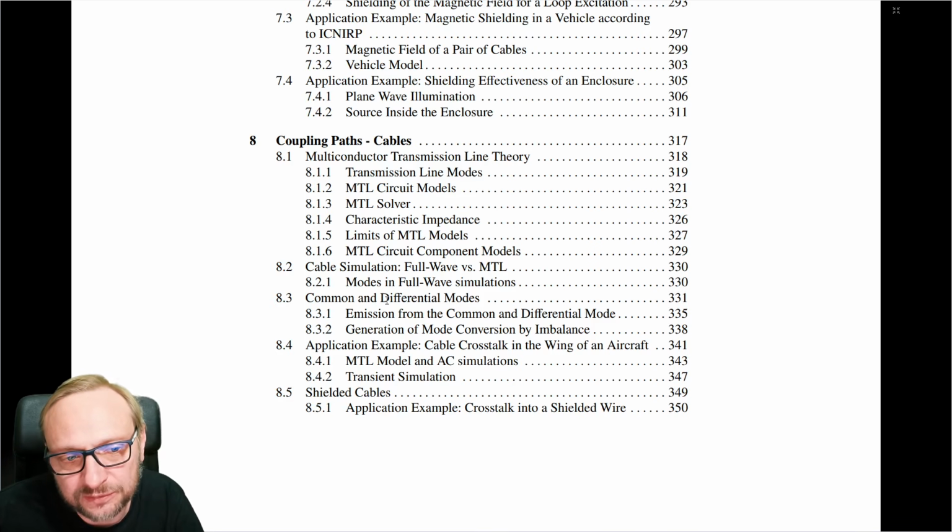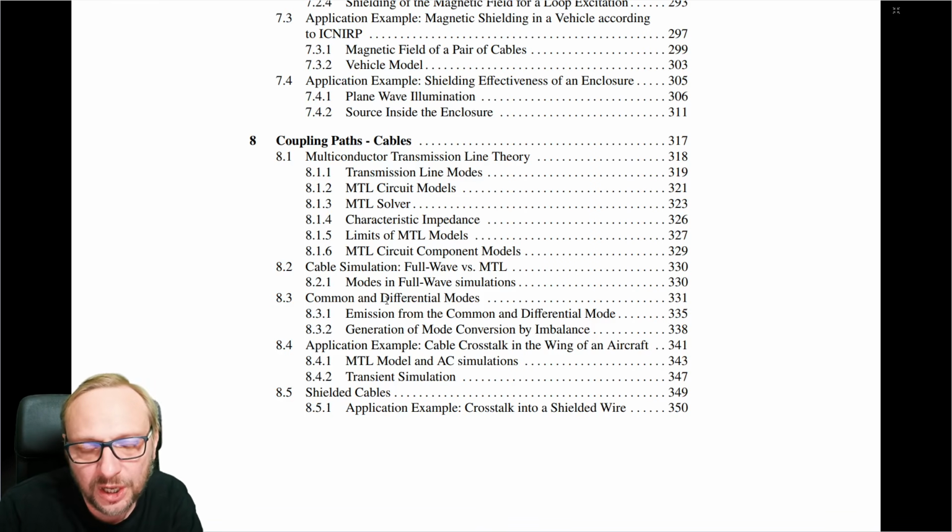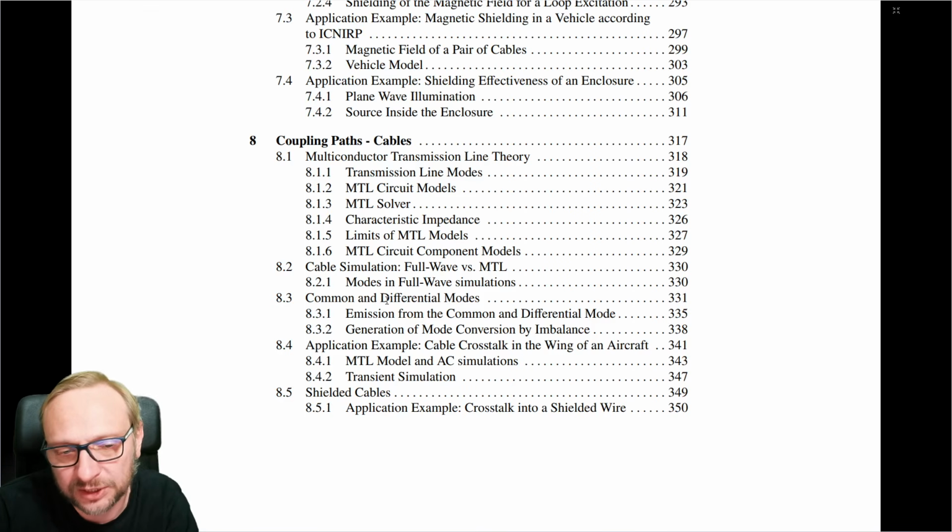But then we discuss, and I think what's quite interesting is 8-1-5 and 8-1-6, where we compare these transmission line models to full wave models. Because many times when I see publications, I often see people saying that this type of cable cannot be simulated in full wave because it's too complicated. Not always is this true. Many times you could simulate a cable if the cross section is not too crazy. You can simulate them with both, and you have to understand the limits of the transmission line method and when to employ a full wave method.